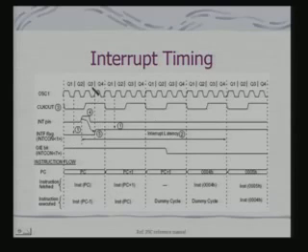Now, the interesting feature is that the time from the point I have got a rising edge of the INT pin to the point where the first instruction corresponding to the ISR gets executed is typically what is called interrupt latency. This is the hardware latency, and this latency is the basic delay which is involved between the raising of the interrupt and that of servicing the interrupt.